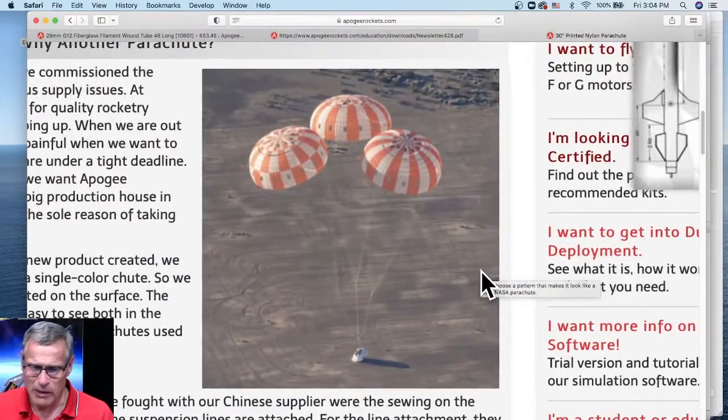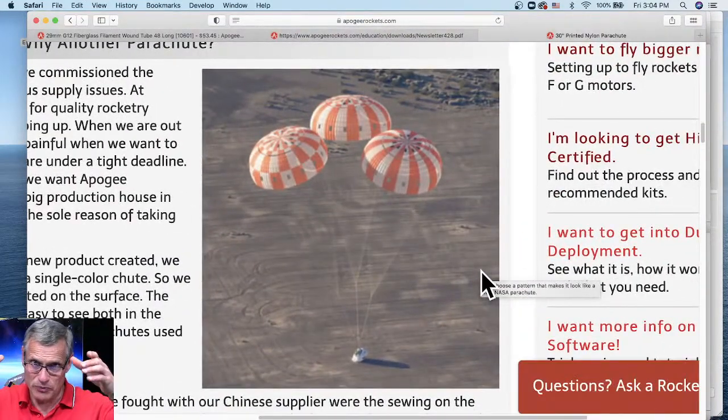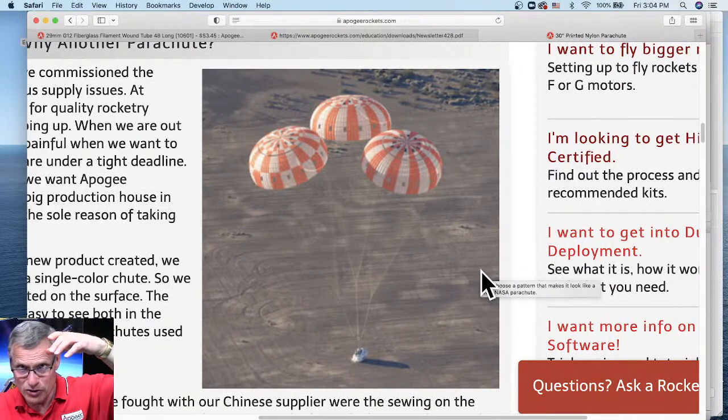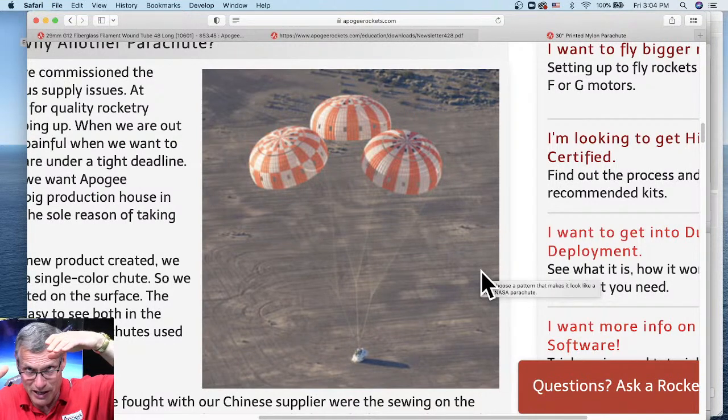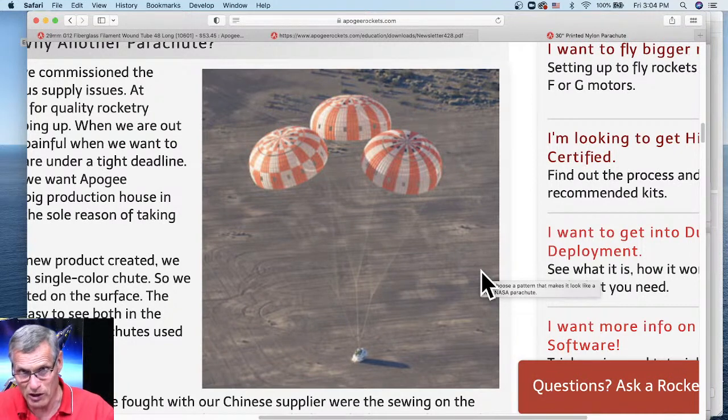Yeah. See, what happens is those parachutes are kind of tilted just a little bit as they're coming down. So instead of getting the full amount of drag by coming down perfectly horizontal, they're tilted a little bit to the side, and so their drag actually goes down a little bit when you have a cluster, because they kind of splay out.